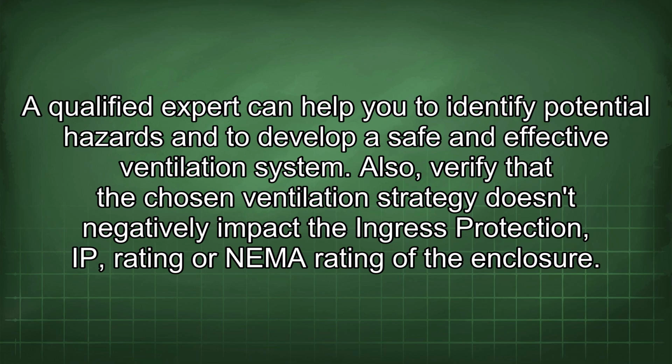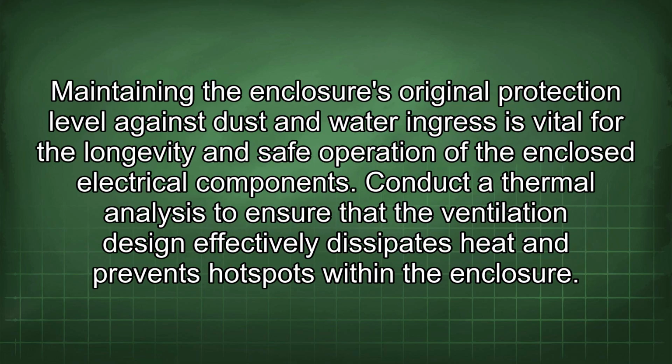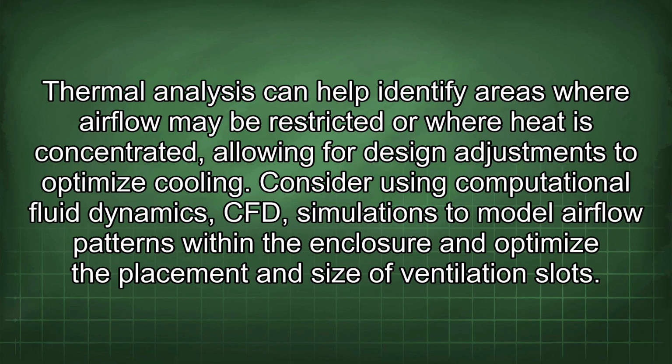Also, verify that the chosen ventilation strategy doesn't negatively impact the ingress protection (IP) rating or NEMA rating of the enclosure. Maintaining the enclosure's original protection level against dust and water ingress is vital for the longevity and safe operation of the enclosed electrical components. Conduct a thermal analysis to ensure that the ventilation design effectively dissipates heat and prevents hotspots within the enclosure. Thermal analysis can help identify areas where airflow may be restricted or where heat is concentrated, allowing for design adjustments to optimize cooling.